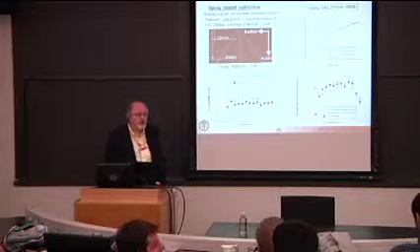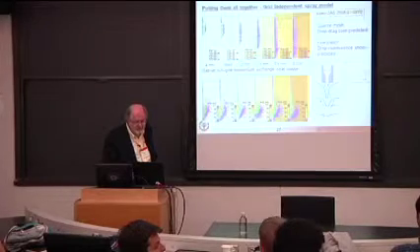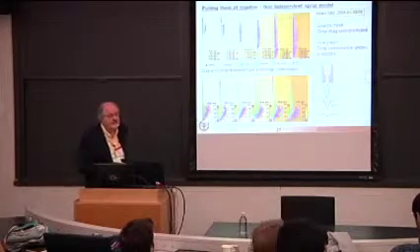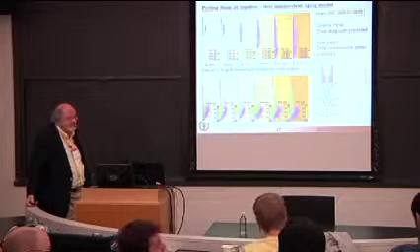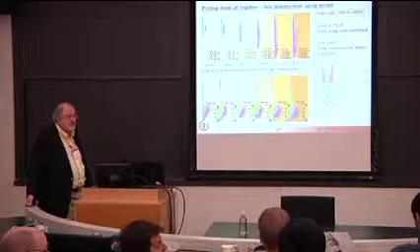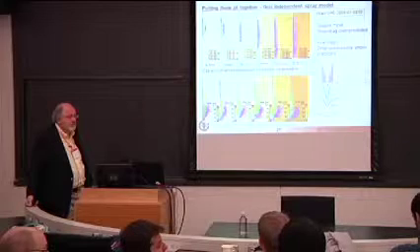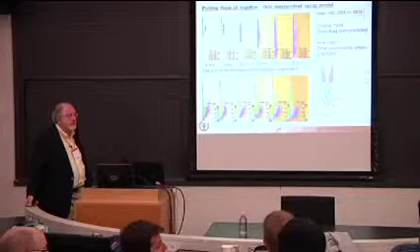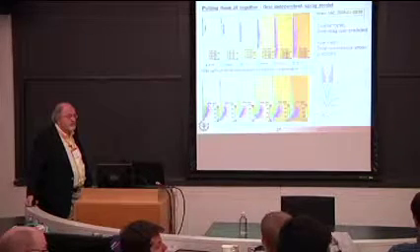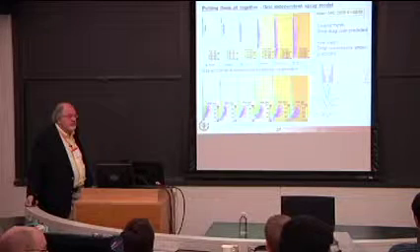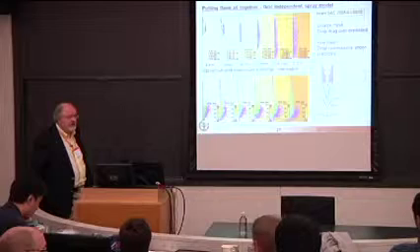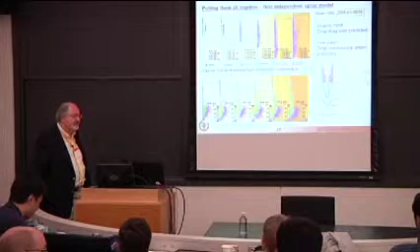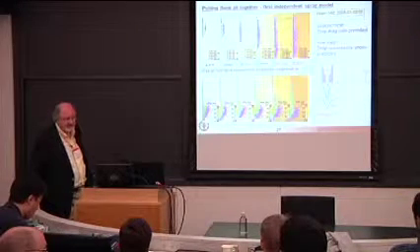With respect to the previous slide, so you have a profile that you apply to, let's say, the cells that are near the jet. And depending on the position of the droplet, then you obtain a velocity that will influence the particle. Exactly. So instead of using the CFD calculated gas velocity, we use a gas velocity estimate from gas jet theory.